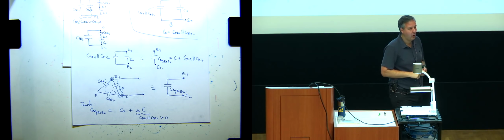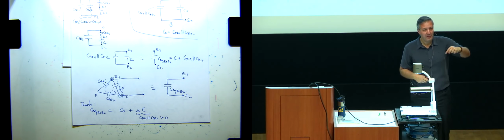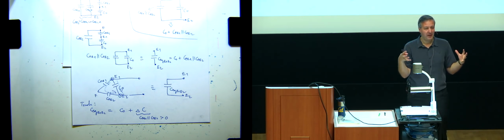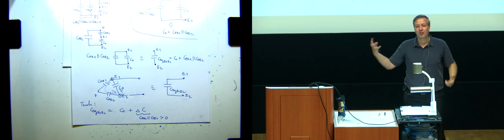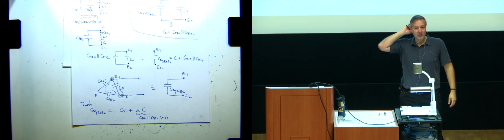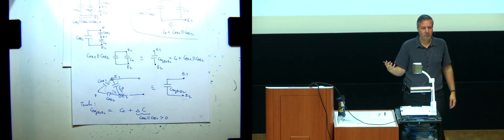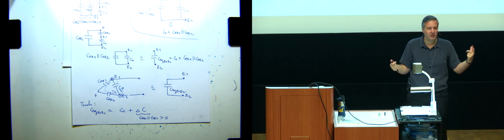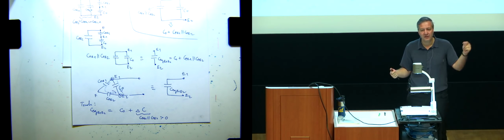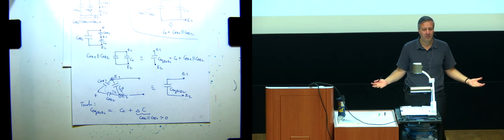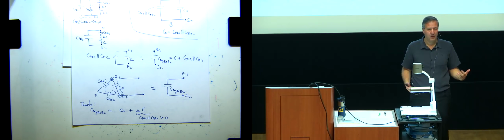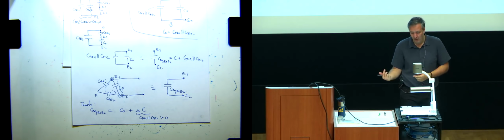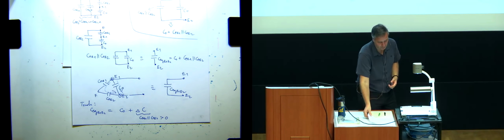What this means is when my finger touches, the overall capacitance between nodes E1 and E2 increases. And that represents information. If I could somehow measure the value of the capacitance, I would know that the finger is there, and then I'm done. Because my whole purpose was to sense the presence of the finger. Then we'll see later at which coordinate it is, etc.